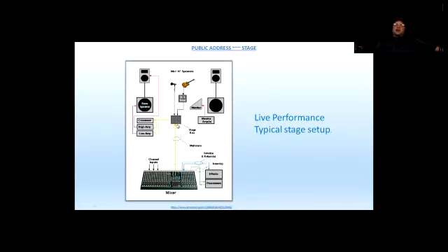Okay, and now when it comes to the stage box for the digital system, you're going to have a category cable, Cat 5e minimum, Cat 6 preferred, that is going to be just one cable. And then that cable is going to be connected to the RJ45 or Ethernet type of port on the mixing board, and all the audio signals are going to be processed by the mixing board and by the stage box, and of course from the output and input peripherals of the stage box.